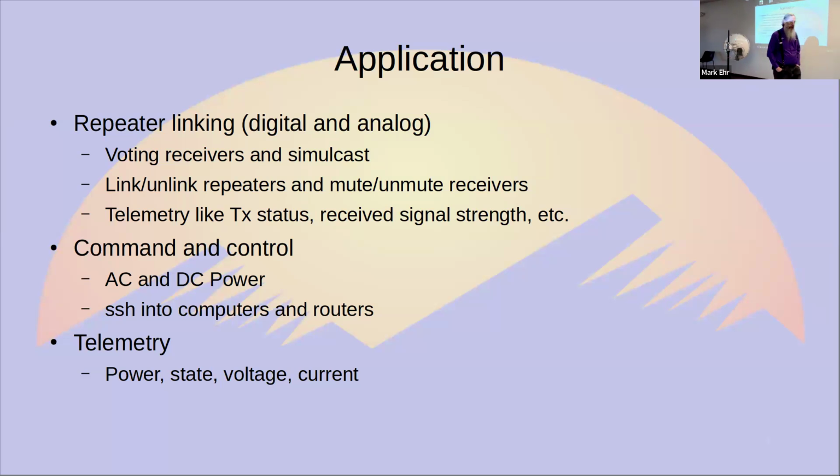And the radios in the 5 gigahertz band kind of tune somewhere between about 5 gigahertz and just over 6 gigahertz if you buy the international version. So the radios themselves are obviously capable of significantly wider spectrum, but they are firmware controlled.